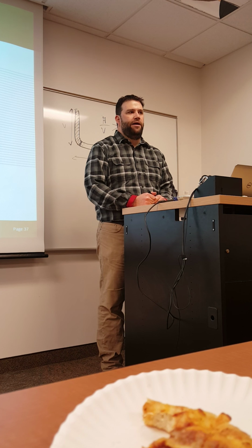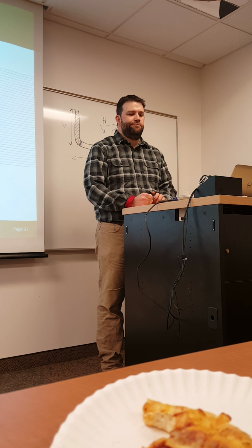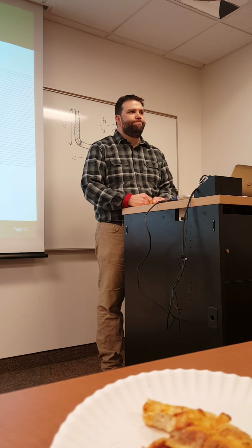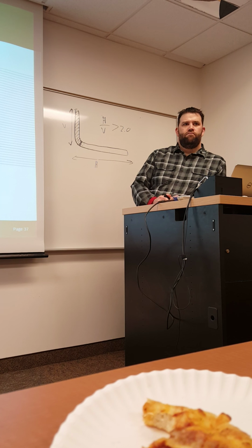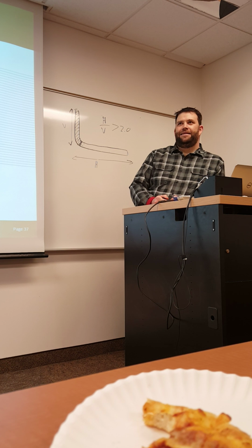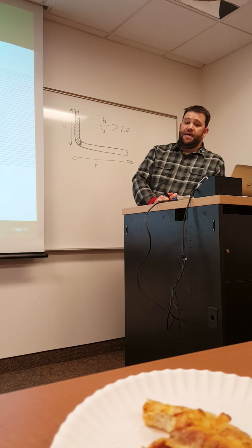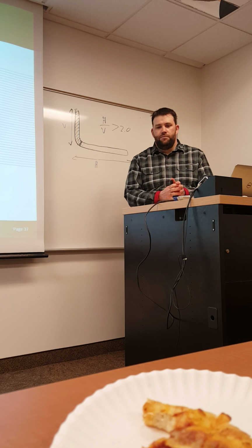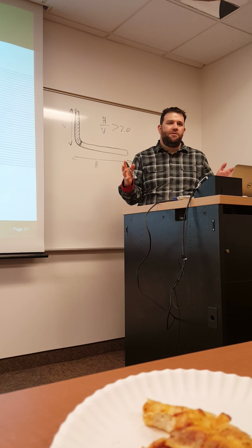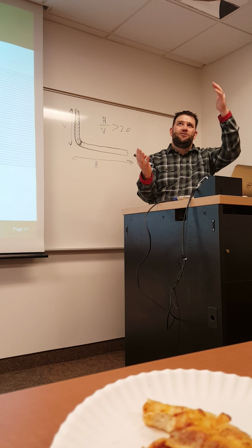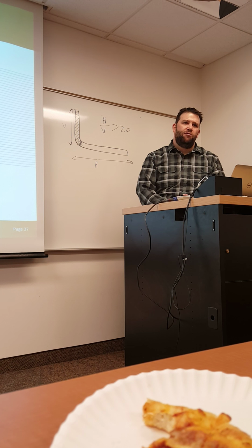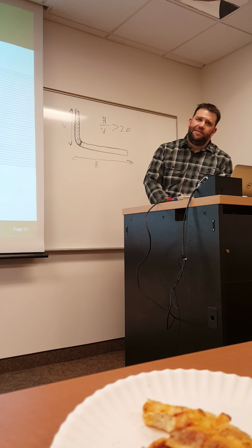But most of the time we're drilling with mud, and mud, you need some mechanical agitation. So I saw that at 120, you think that that's where that viscous coupling is getting the size of the tool joint. There's another jump at 180. What's your thought? I don't know. It might be that there's another turbulent regime that we hit, or maybe the viscous coupling layer starts to hit the edges of the hole. I don't know. We really don't know. That would be an interesting thing to figure out, though.